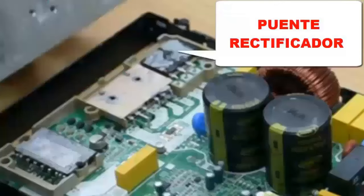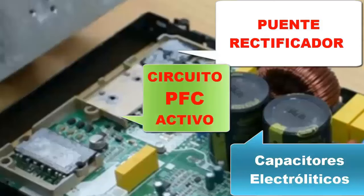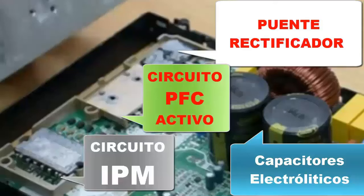For example, most units powered at 220 volts are designed to operate within a voltage range of 170 to 260 volts. If the voltage falls outside these limits, in this case below, the system activates the PC10 error as a safety measure.